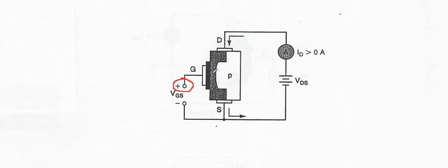And that voltage that starts to create a channel by pushing back that P region, that's known as the threshold voltage. If you remember, VGS threshold is unique to E-MOSFETs. So yeah, it takes some amount to even get it going.